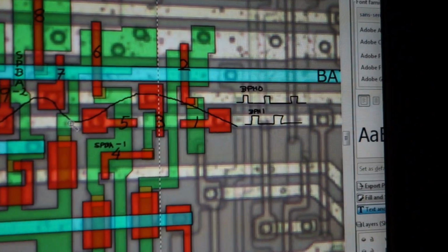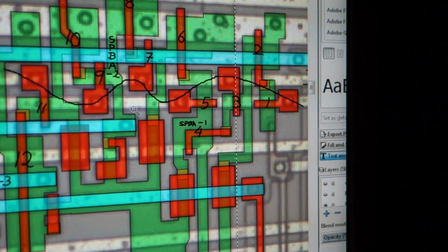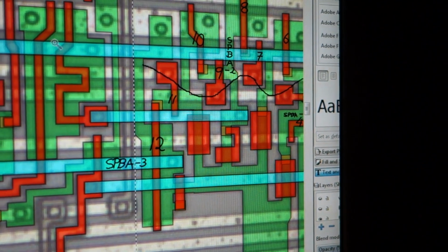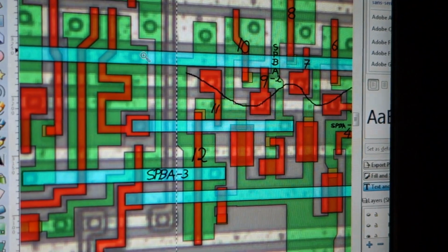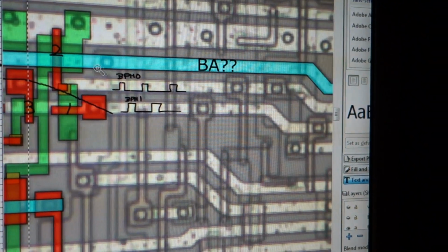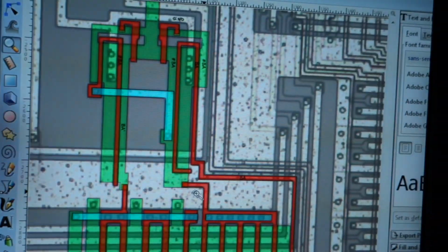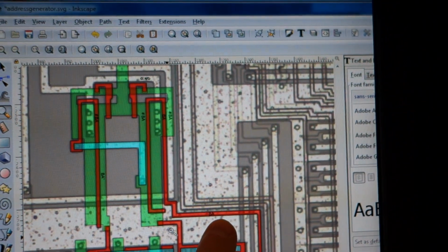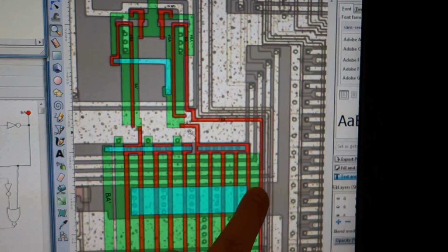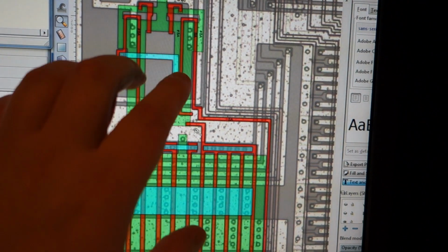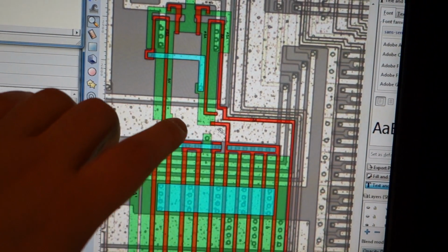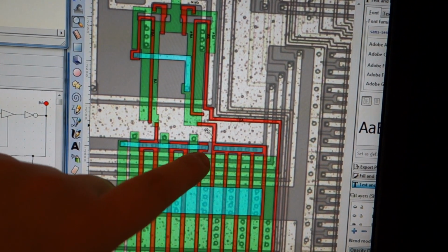So let's look at this part first, and then we can look at this down here afterwards. So basically this circuit goes over here into this buffer, which drives BA, and BA is bus available. So we have bus available up there. It goes down to the output pin driver, and the signal all the way from that transistor we saw comes up here into some decoder, or demultiplexer.